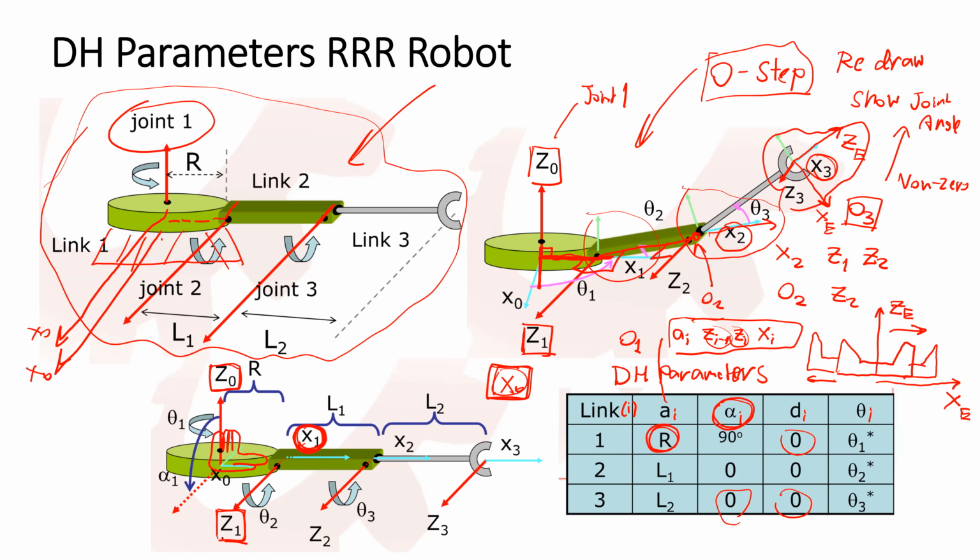In this case, the thumb will point along the angle between Ci minus 1 to Ci about the Xi axis. So the thumb points in the X1 direction. The finger points to the C0 and then rotates to C1. And this angle is 90 degrees.